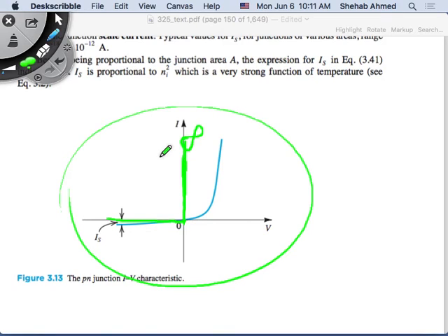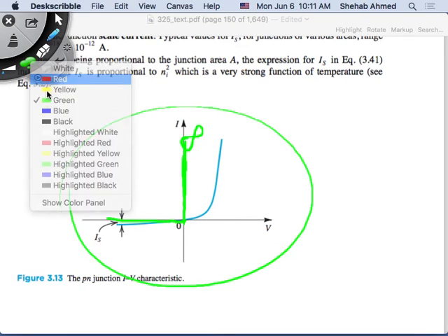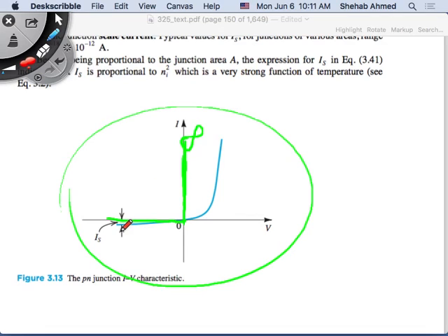If your circuit doesn't limit that current and you put a short circuit across it, the diode is happy, it will conduct. But it will conduct not knowing it's getting hot and burnt, right? But that's why you design your circuits to take care of that. So we discussed one model, the ideal model. Then we discussed another model that is called the piecewise linear model, meaning the current here increases all the way to IS.